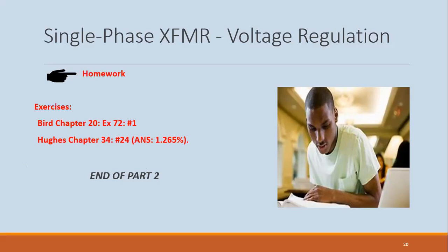Oh. So the impedance will help to determine the magnitude and angle of the current. So the voltages are still 120 apart. Yeah, the supply voltage didn't change. That is an understanding that you need to have, right? The supply voltage didn't change. The only thing we did was change one phase of the load.